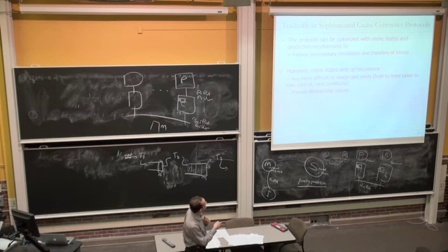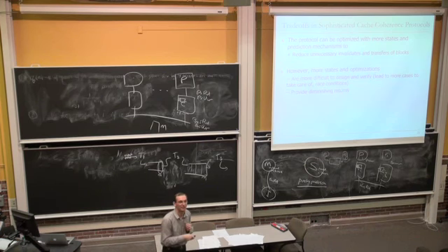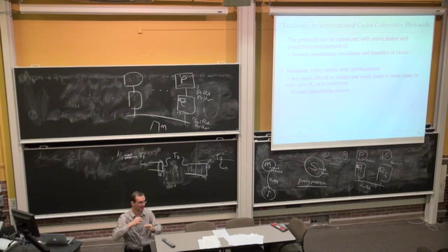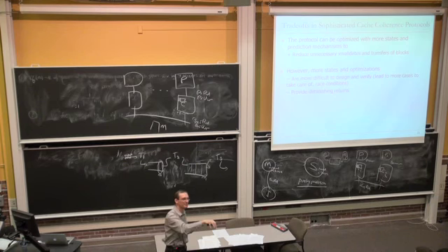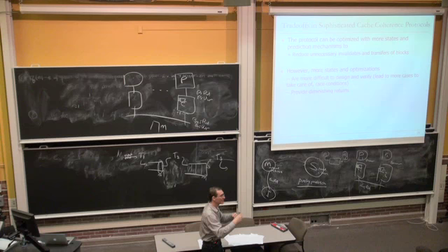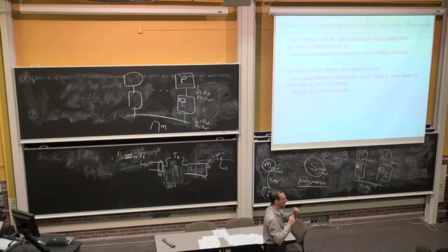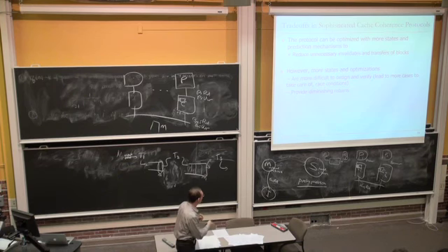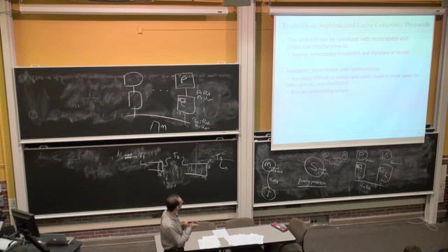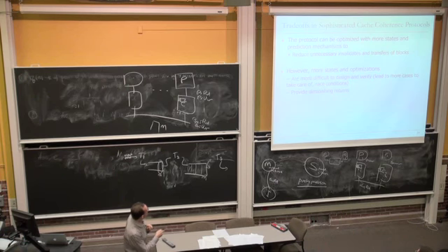More states and optimizations: well, first, usually they provide diminishing returns. Going from MSI to MESI was a big step, if you will. Going from MESI to MOESI is not as big of a step. Depending on the workload, on average, it doesn't provide as much performance as going from MSI to MESI. Going from MOESI to your favorite protocol that you might want to do for Lab 7, I don't know. Maybe it's also a diminishing return, unless you find something that's missing in a fundamental way in all of these protocols. The second thing is they're more difficult to design and verify.